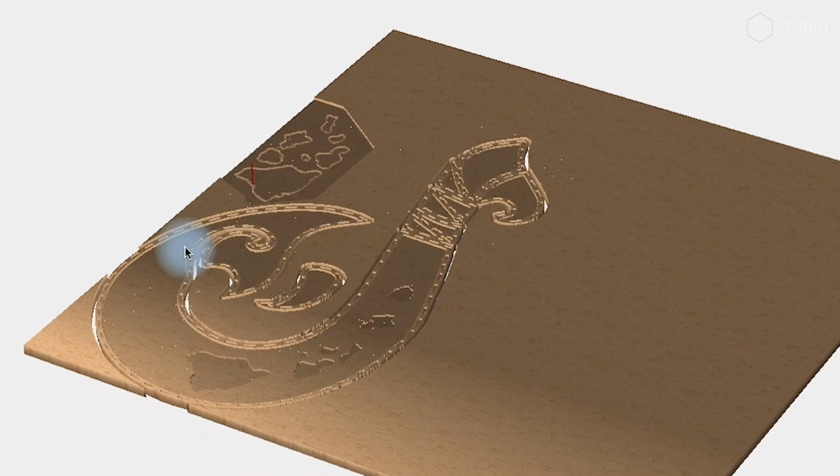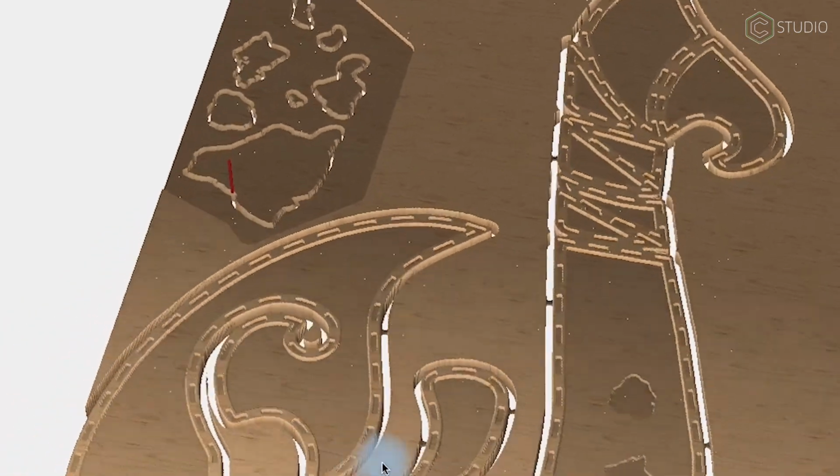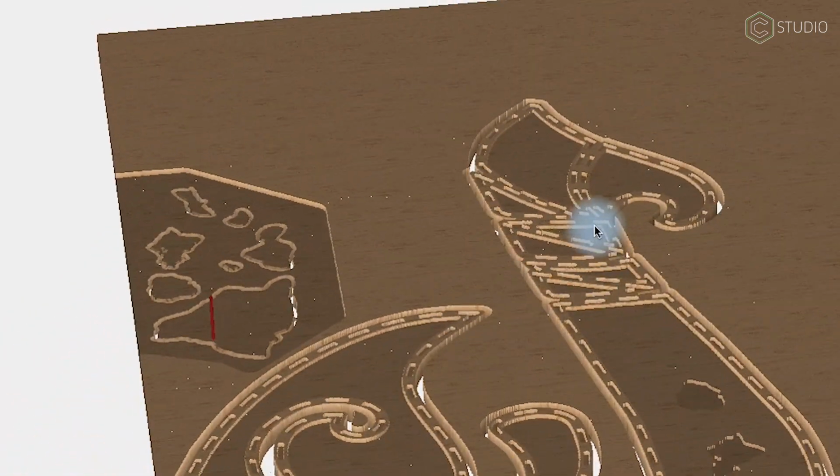That ended up not quite being what I wanted. Later in the final version, I faced off the area for the islands by 6mm. This made them 6mm thinner or shorter in the design, and I mounted them in 3mm deep insets for a little extra overlap when glued into place.